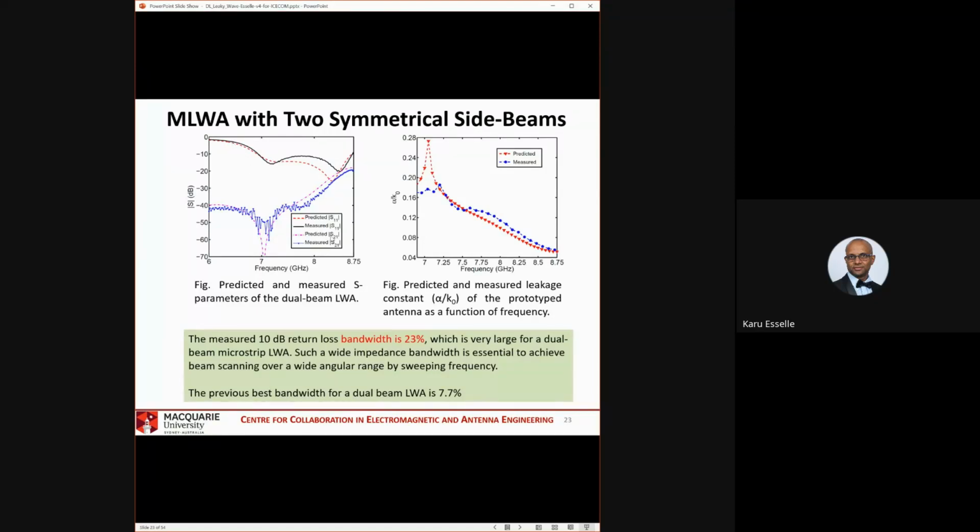The S21, remember from yesterday, this is the loss. This represents power that's going to the load, match load. And we don't want to have that, we don't like that, right? It's all total loss. But that is very, very small, it's minus 40 dB. Only at very high frequencies you get, still it's quite a small amount of transmission or loss at the match load.